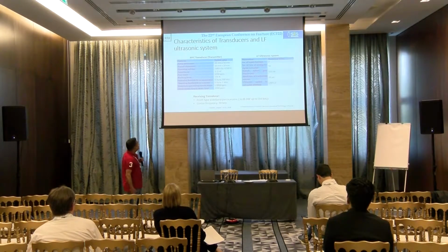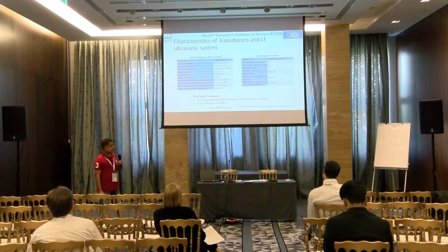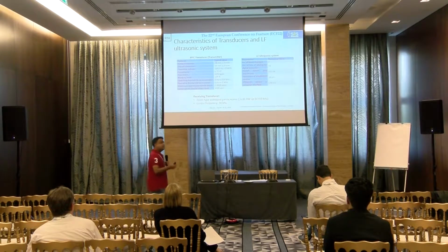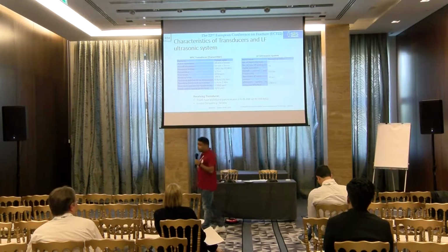These are the characteristics of the transmitting and receiving transducers and the low frequency ultrasonic system. The MFC transducer is working as a transmitter, which is a macro fiber composite transducer developed by NASA. It is very thin and compact in size, can be glued and embedded on any structure, and is a highly efficient transmitter and receiver of the fundamental guided waves.